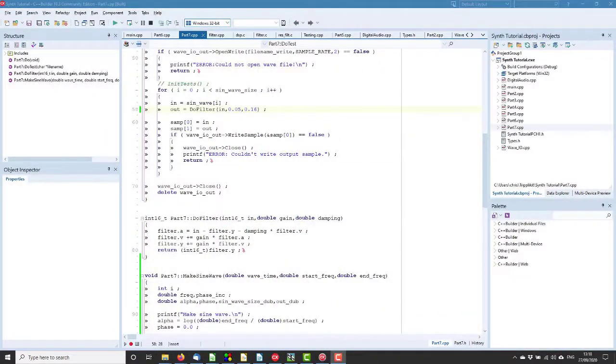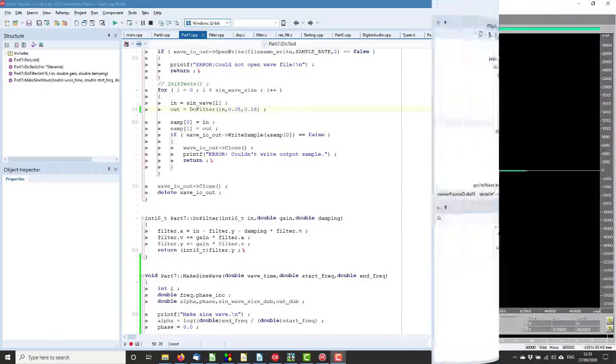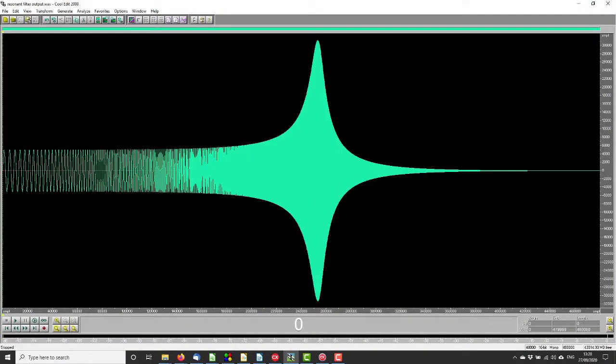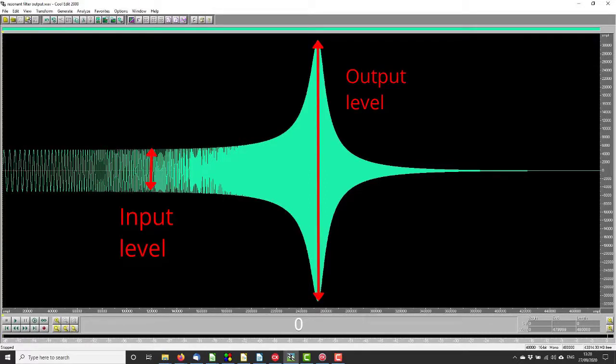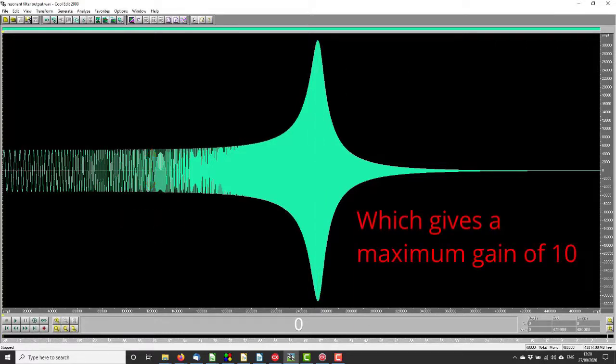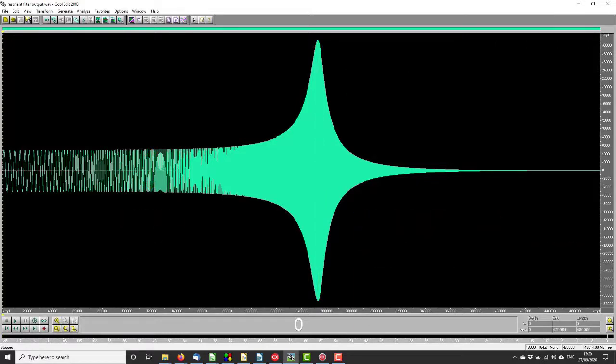Now, we developed our filter using floating point arithmetic, and I'd strongly recommend that you do use floating point wherever possible. I'm now going to go into a bit of detail on the filter implementation using integer arithmetic, and I hope this will demonstrate why floating point is much better. The first point to note is that a resonant filter can have gain. In the mean green we're allowing for a resonance of up to 10, and if we have two filters in series to give a 24 dB per octave cutoff filter, this could have a gain of 100.